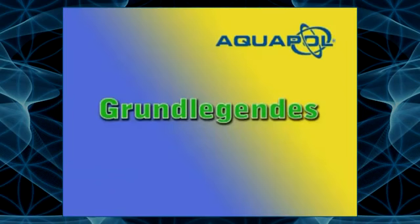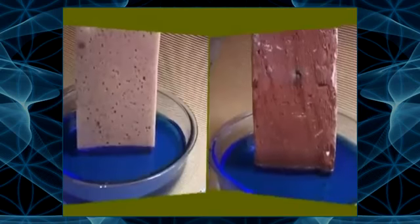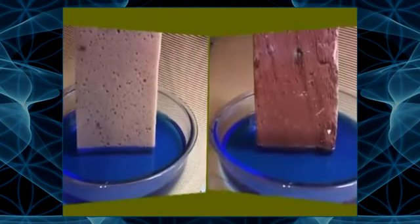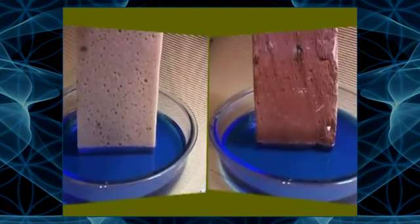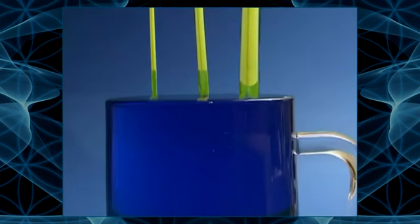Basic data. From building physics, we know that water is absorbed by building materials like a sponge. This effect is referred to as the capillary effect. If we put two materials of different porosity into a water bowl, we will observe the following. Building materials with larger pores absorb more, while those with smaller pores absorb less. The thinner these pores are, the more capillary they have, the higher the water rises.